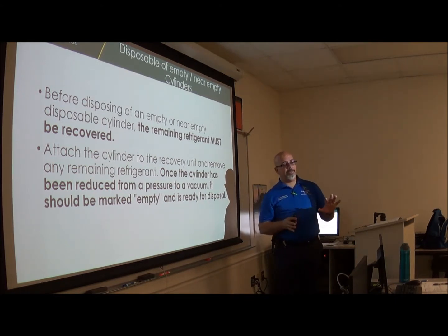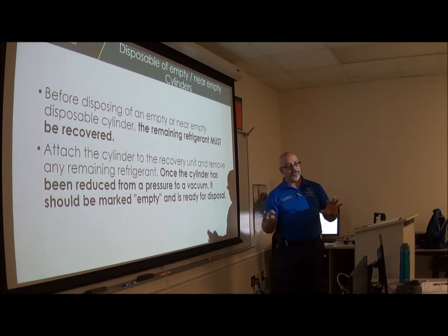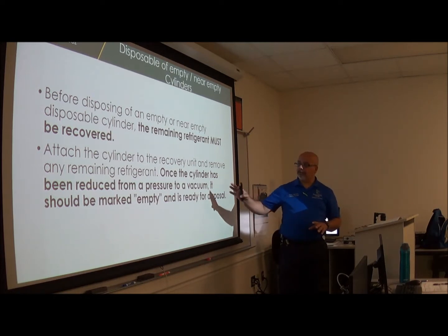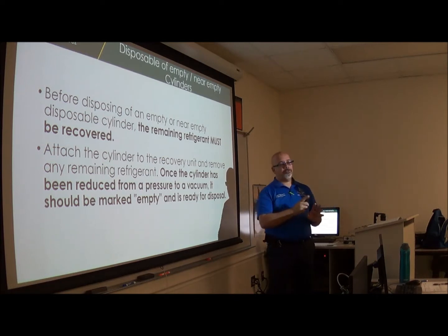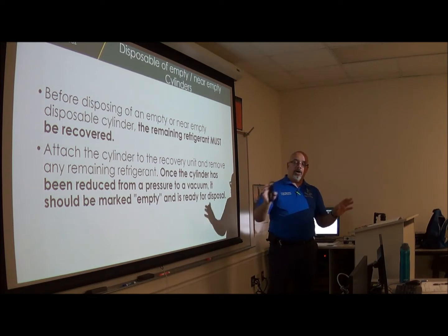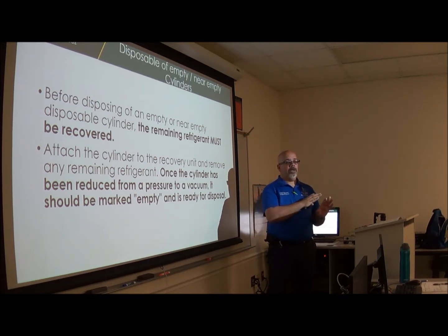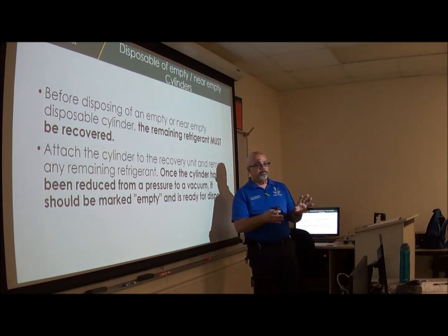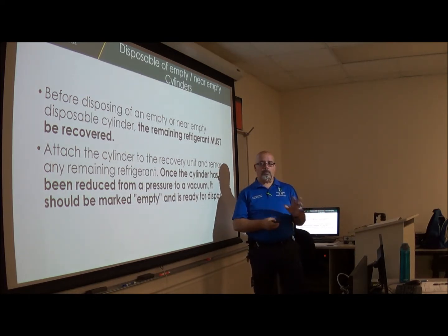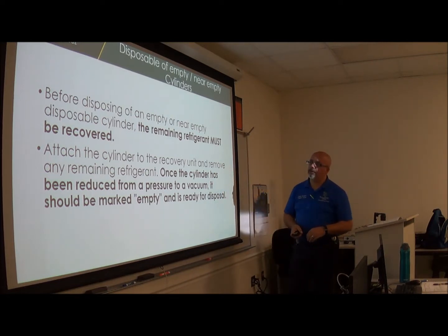There is a 5-minute vacuum testing that we do. After you take all this refrigerant out and it goes into the vacuum state under 0 and you turn off the machine, it's supposed to not move or start going up again. The rule is 5 minutes, okay? But when you do a second vacuum, the rule is 2 minutes. And we will talk about that also here.